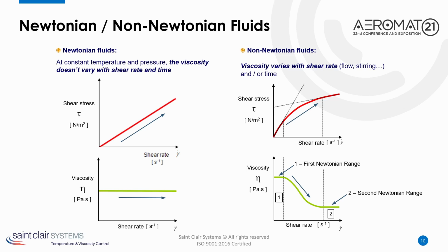For high viscosity fluids, like sealers and adhesives, it's often better to design the dispensing system for laminar flow so as to work in the first Newtonian range, where, with coatings, it's often easier to add agitation and turbulence so as to work in the second Newtonian range.